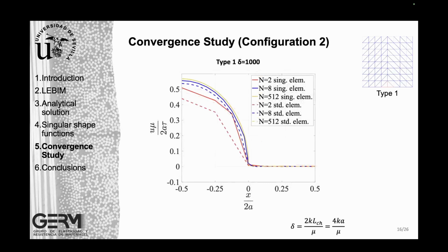If we go closer, and also if we increase the stiffness of our interface, the results we obtain tend to go to the classical crack solution. In fact, if we remember the classical solution of a crack, this displacement solution is very classical in fracture mechanics. So we see, for example, that when this delta parameter is higher, the displacement here on the spring interface is almost 0. So it means that we are almost close. And once again, the results tend to the solution of the very large number of elements.